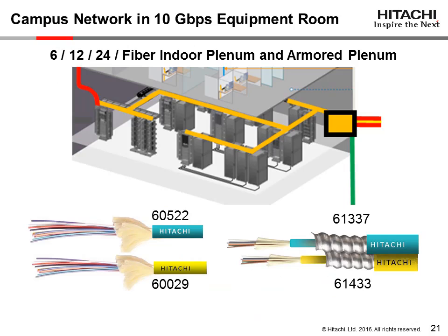The service entrance terminates in the equipment room, which houses the electronic communications equipment. The equipment room most likely contains servers, Ethernet switches, and routers supporting other satellite building locations in the campus network. Within the equipment room, either copper cable or fiber optic cables may run between various equipment depending on the complexity and size of the campus network. But if fiber optic cables are located within the equipment room, it is very likely they are indoor plenum rated and may be armored due to the project requirements or for additional safety and security purposes, connecting services switches, or linking up the backbone cable's distribution data throughout the rest of the network.